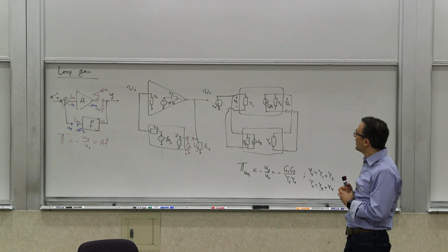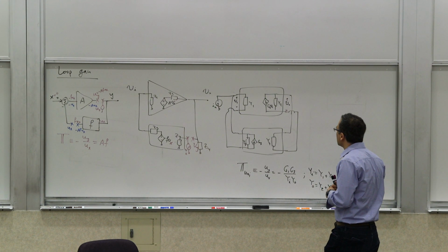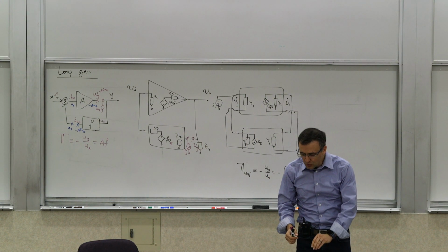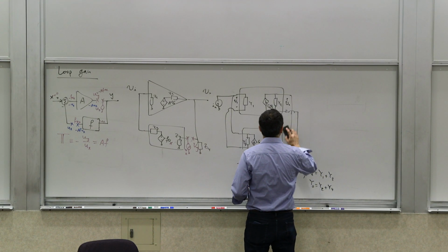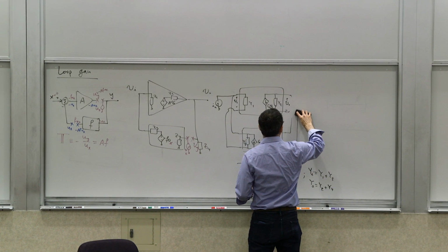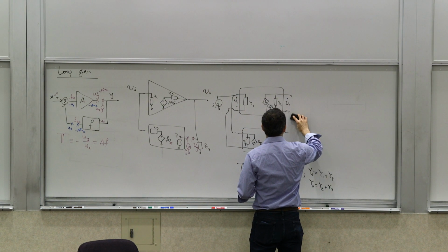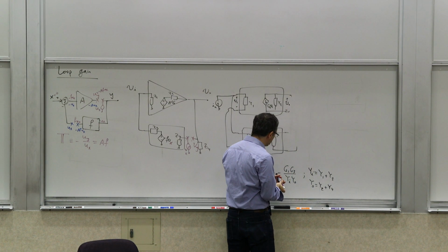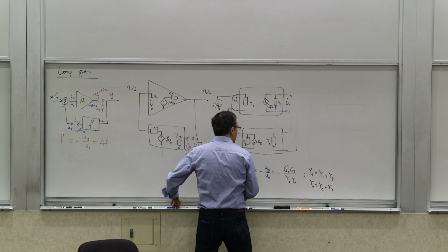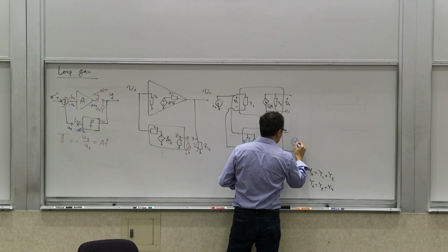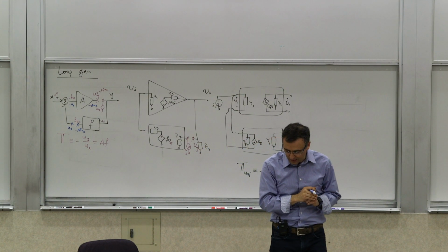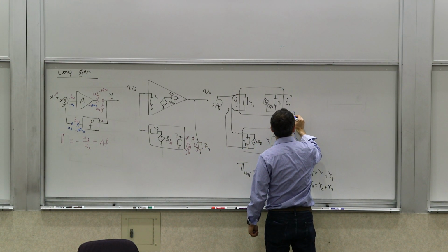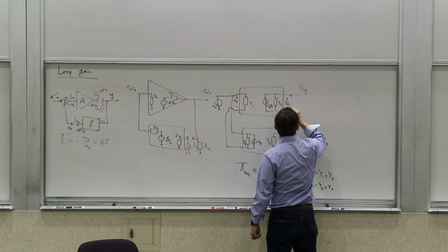Or you could say, you know what, what if I just broke it the way we described it? What if I just broke it and induced only a voltage source? Let's break this loop here, somewhere, it doesn't matter really, and say, I'm just going to apply a voltage Vx here, without taking the loop loading into account, and monitor what comes out, Vy.